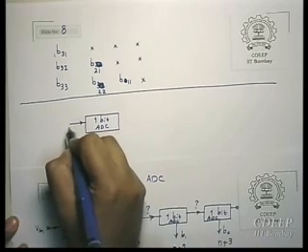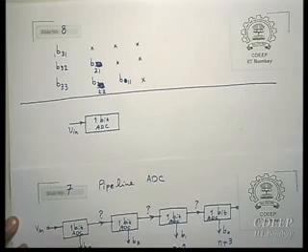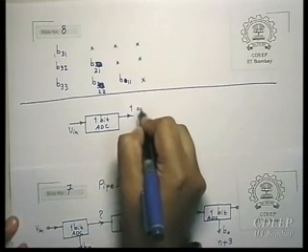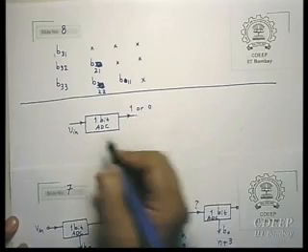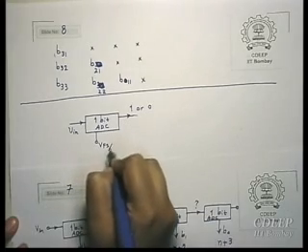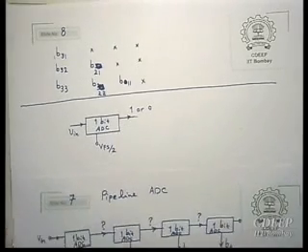And you have a track and hold version of input. So therefore at the output you will get either 1 or 0. Therefore you need only one reference level, which is V full scale by 2. Right? This is your reference level.